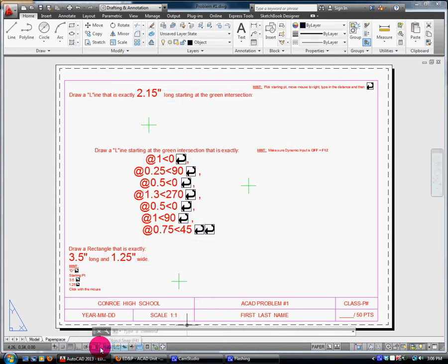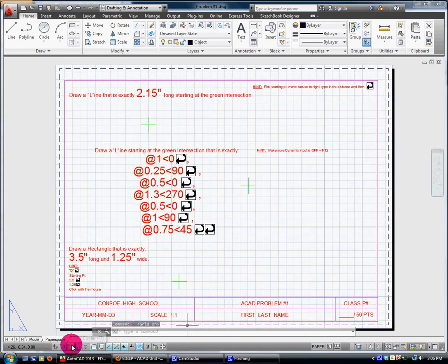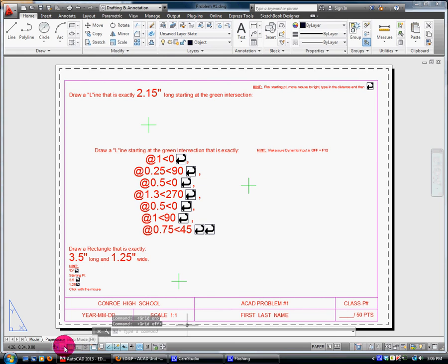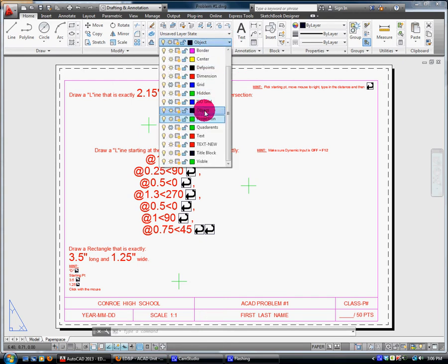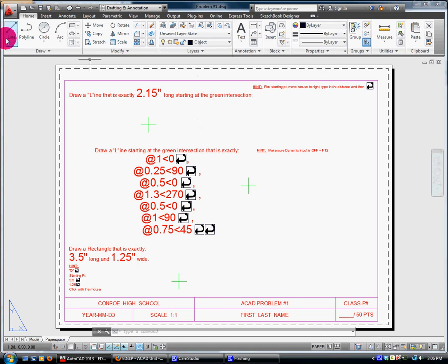And you just come through next. So here would be object snap. Oh, 3D object snap, polar tracking, tracks it. Ortho mode forces it to go perfectly up and down. Grid display, if you click on it, shows a grid. All the different tools down here do different things, so you can play with them if you need to look at it. Right now, we're just going to go ahead and draw. All right, I want to make sure that my object layer is current, so I click here, and I click on object layer, it's current, and I go to line, or I type in L enter, either one works.